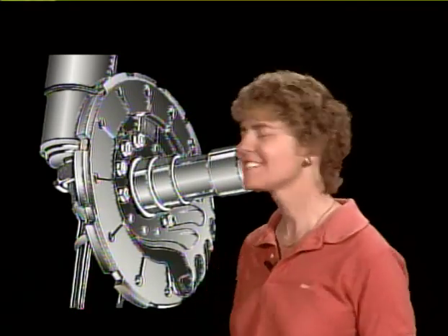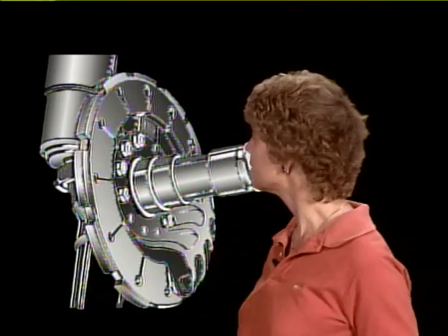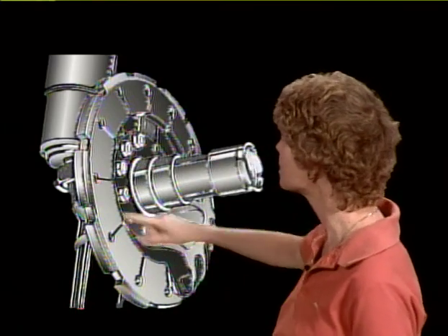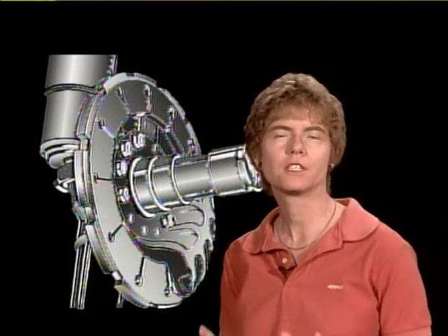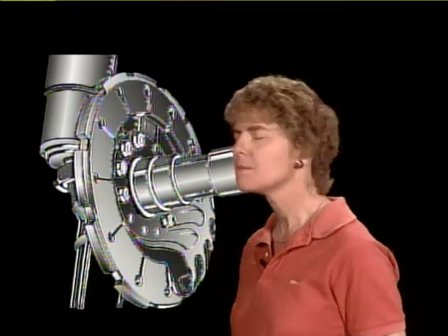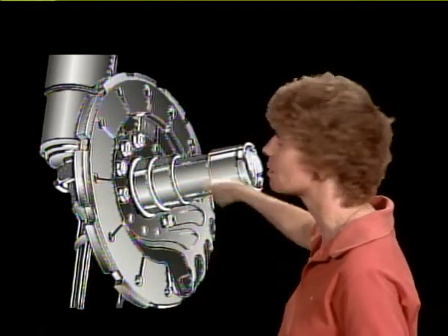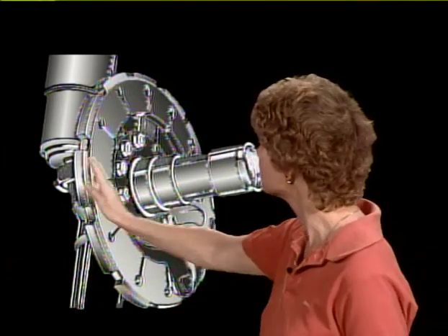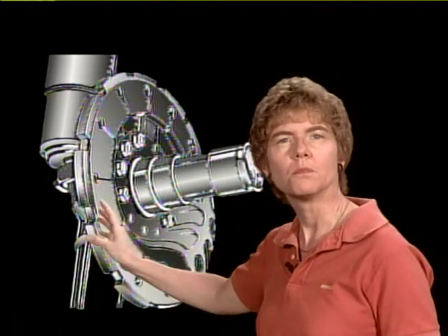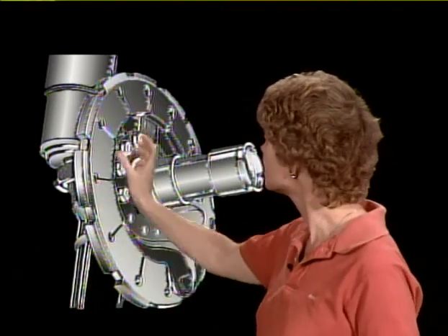Now, we've talked about different ways to actuate the brakes. Let's talk about the brake assemblies themselves. On small general aviation aircraft, what you'll typically find is this type of brake system, which is single disc brakes. With a single disc brake system like this, you want to make sure to keep equal pressure on both sides of this rotating disc. The way that you assure equal pressure on both sides of the rotating disc is by keying the disc loosely in the wheel so that it can move from side to side. And by moving from side to side, you will keep equal pressure on that rotating disc.